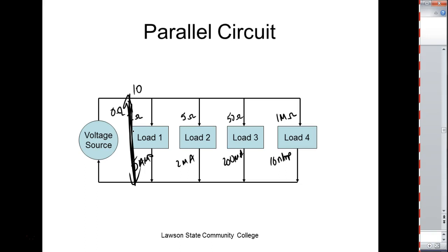So that's why conductors are rated in ohms per 1,000 feet. If we look at a 24 gauge wire, it says something like 30 ohms per 1,000 feet. Right? You understand that? So how much would it have for 1 foot? Well, our instruments wouldn't be able to measure that. So if I put that wire across something, then the current flow through that is going to be extremely large.